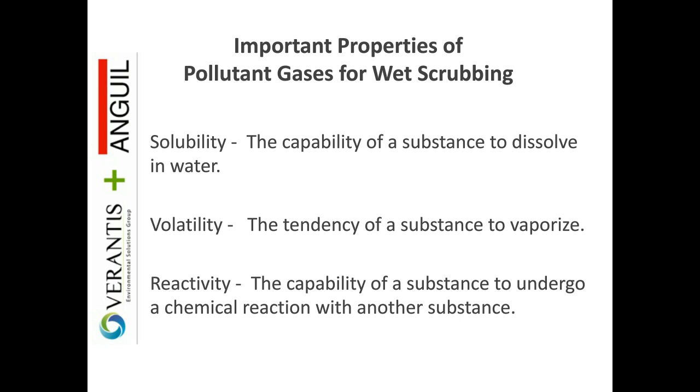So I know, for example, sulfur dioxide, you can find some published data which tells you that it's got a solubility in water. You would not be able to economically scrub sulfur dioxide using water only in most cases because of its very high vapor pressure. So when you consider a pollutant for wet scrubbing, if it's soluble and has low volatility, then it's probably a good candidate for water scrubbing.